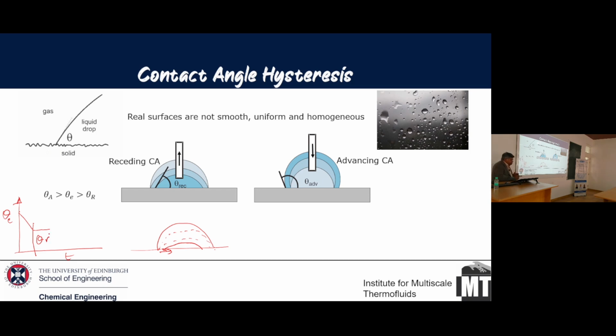That's why I say that the equilibrium contact angle is just based on the thermodynamics, on the amount of material placed on the system, and it is completely experimentally determined. There's no hard and fast rule that you can determine an equilibrium contact angle theoretically. But the receding contact angle is the point at which the droplet starts to move as you take off more of the liquid.